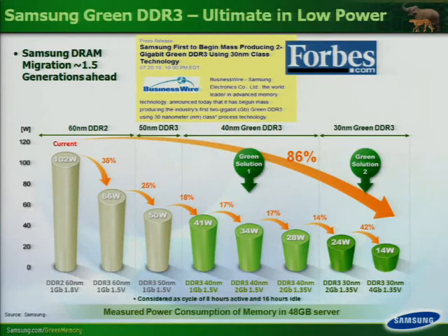Well, this is just to show you what we showed you earlier on: even alone, if you take the predecessor FB DIMM technology and you look at what Samsung offers in terms of their DRAM, we're able to achieve about 86% power saving at DIMM level. In this particular comparison, we've compared the power consumption for about 48 gigabytes of memory. If you use older technology, such as DDR2, it consumes about 102 watts. If you use Samsung's latest technologies, you can go as low as 14 watts.